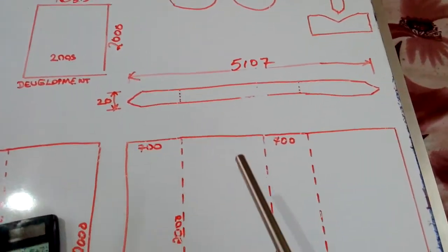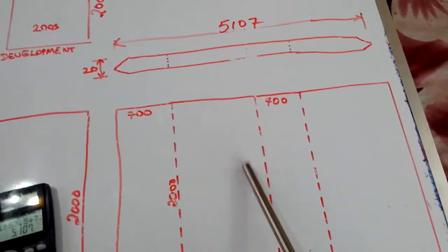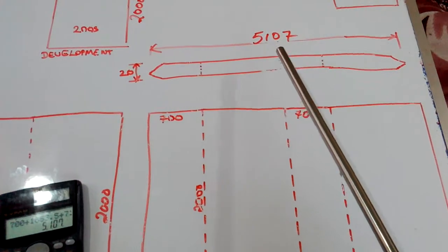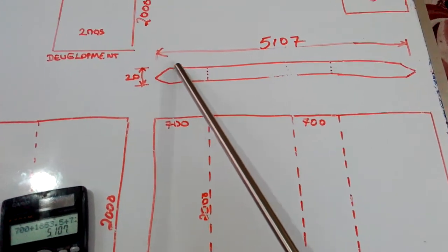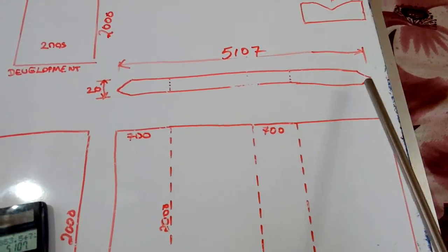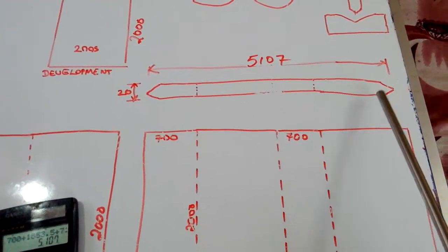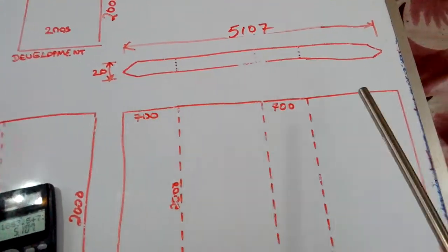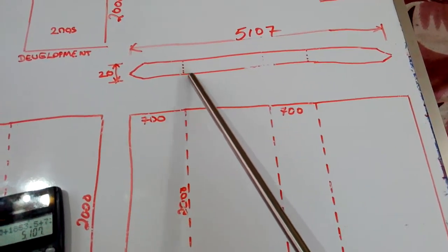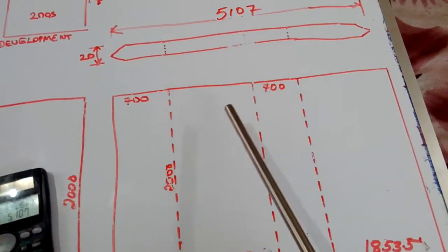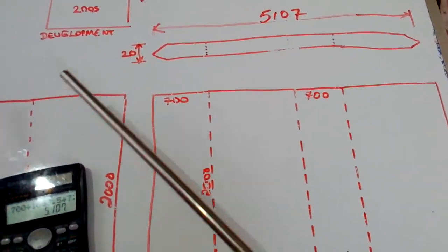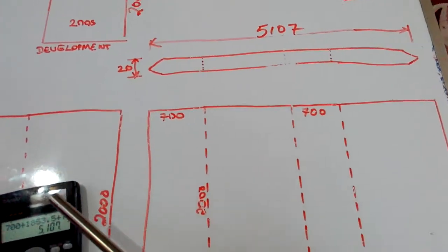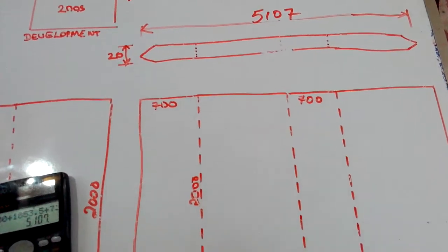So this job's view from here is this one. Why did I write this? I had to indicate these sharp marks. What does this bevel indicate? It is indicating welding. Those areas we have to weld. After cutting, we have to bend here. We will make rolling in this area. Then it will come like this. Again the straight area comes. Again this rolled area will reach here. These two portions, this one and this one, will match together. Afterwards we have to weld it.